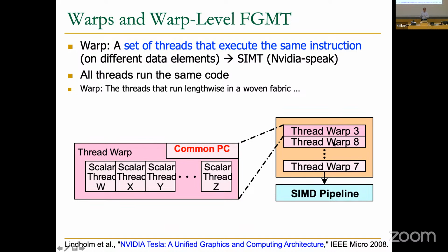Well, you need to make sure that the same thread doesn't go into the pipeline until it finishes one instruction in the pipeline. Basically, no two instructions from the same thread should be in the pipeline. That's the basic principle of fine-grained multi-threading, right? That ensures that our pipeline stays simple.